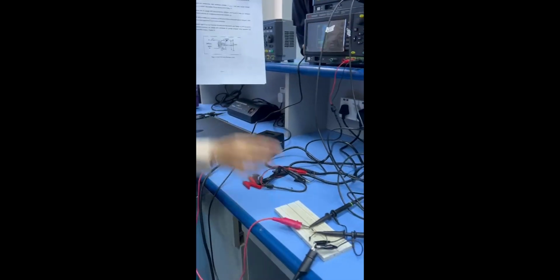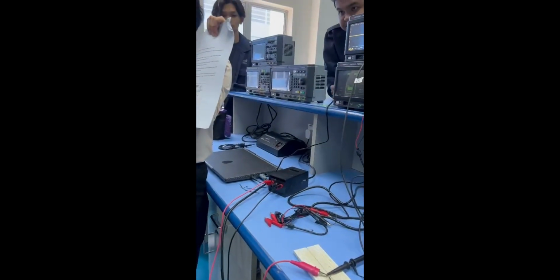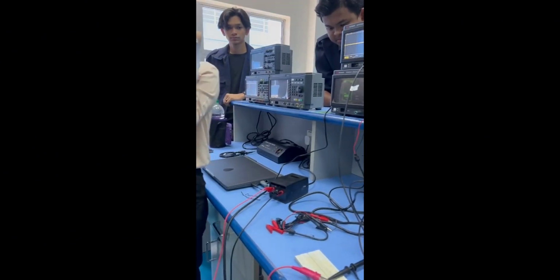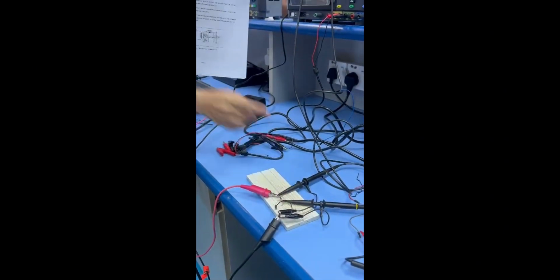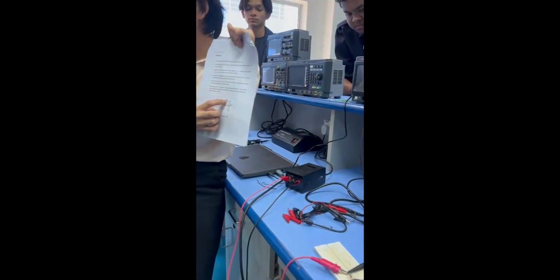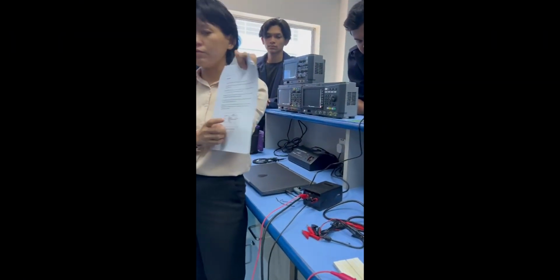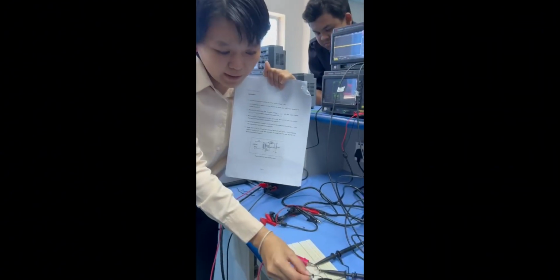First, the red wire, you have to connect from the transformer to your diode. After you connect to your diode, the black color goes to the silver side of the cathode. Silver is the cathode. Then connect to this resistor, 1 kilo ohm. Check your resistor whether it's 1 kilo ohm or not. If not, you took the wrong one. Check with the multimeter. Then go to the ground, the black color ground.